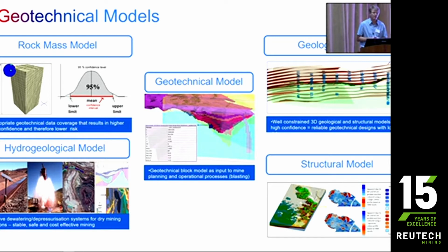I'm not going to try and guess how many mines actually know where the water is coming from underground and how corrosive that water is, because we start these mines and they last for 50 years. You've got to take into account if that water is corrosive when you do your design up front. You've got to design for 50 years, or build in some rehabilitation along the way. So for me, this is the crux of the geotech design, and monitoring permeates through all of this from the start of the project.